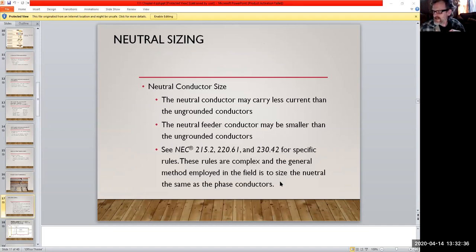All right. Now we come to something a little more specific to residential and commercial aspects, where we get a neutral. And the neutral comes out from the transformer out on the pole or underground, whatever case you got. But it comes from the transformer, and what they do is a center tap on that bad boy. So you'll have two hot lines coming into your house, okay, both from the outer ends of the transformer. Each one's 120, and then going back to that center tap of the transformer. So it's 120 and 120, two main feeds, right?